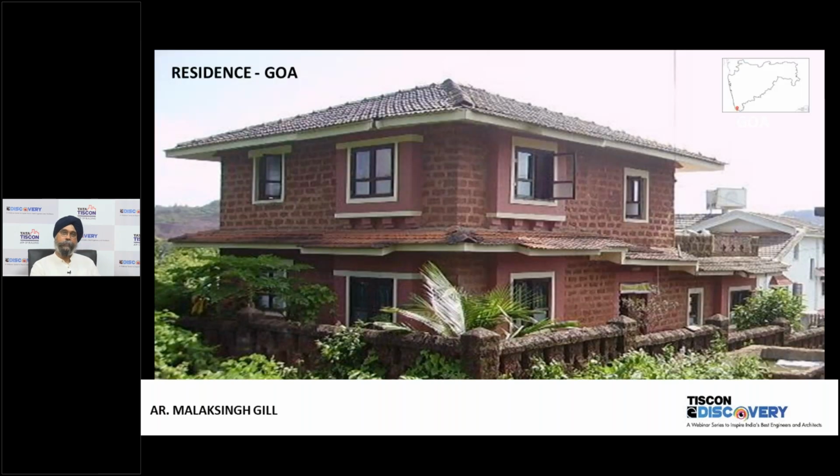Now here's a building in Goa where I again took the cement out of the walls. Now interestingly, this was the first time I made the walls with mud mortar. It has an RCC roof, an RCC filler slab roof with Mangalore tiles on top of it for cooling and for preventing leakages. And it has mud mortar in the entire walls.